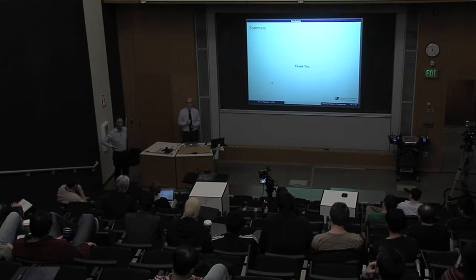It depends exactly how far off they are. If they're only off by a few percent in terms of their mismatch, what ultimately happens is if you just let them open circuit, their voltages would be a little bit different. And so ultimately, their peak power is a bit different. So the open circuit voltage compared to the voltage at which the peak power occurs is usually about 70, 80% from the open circuit. And so you end up bringing those voltages down anyway. And so you're always going to be operating, unless one is really far down because there's something majorly wrong with it, you're going to be operating both and pulling current out of both.